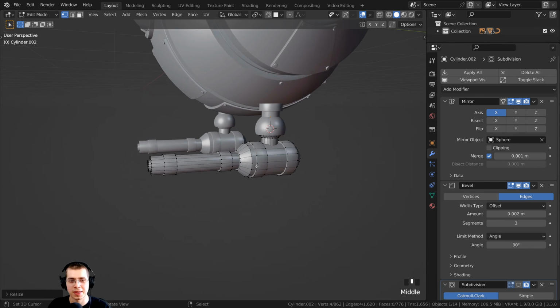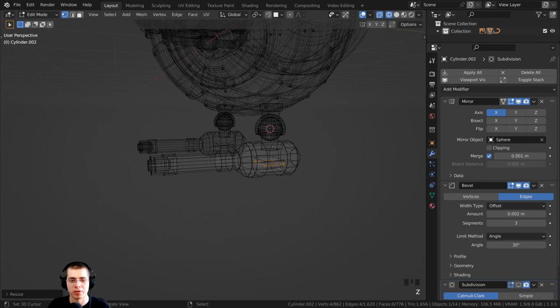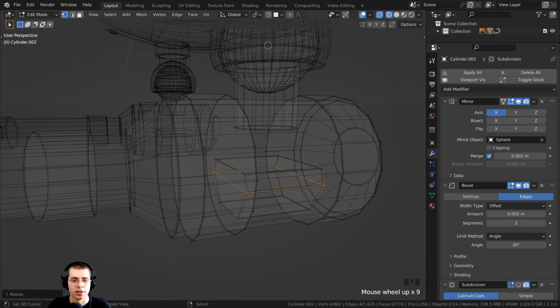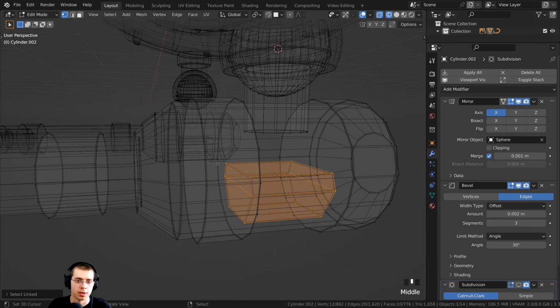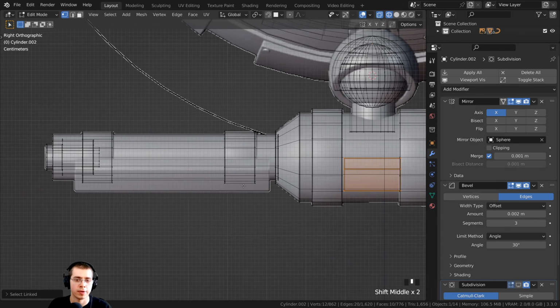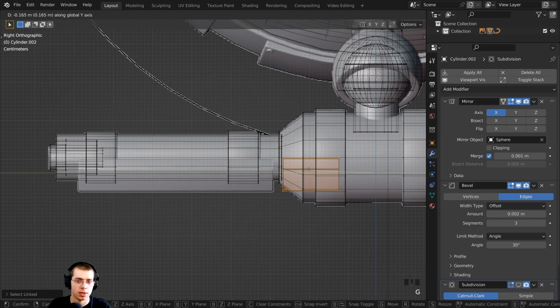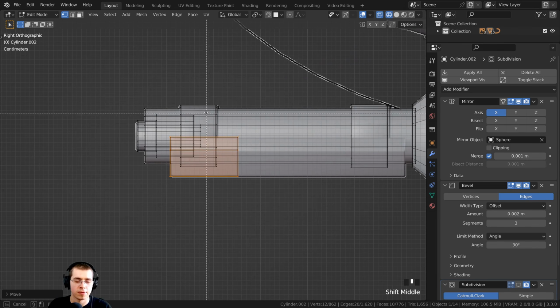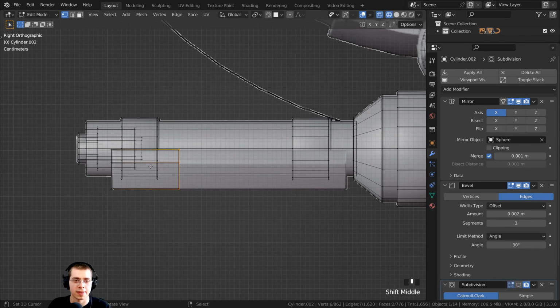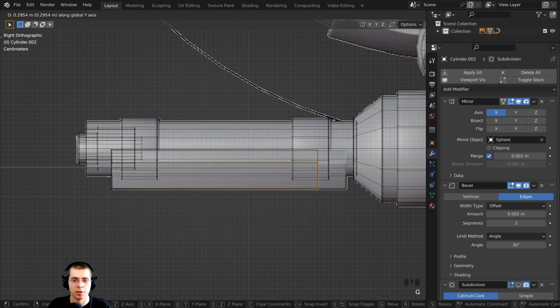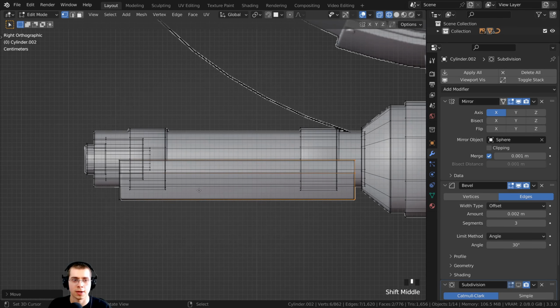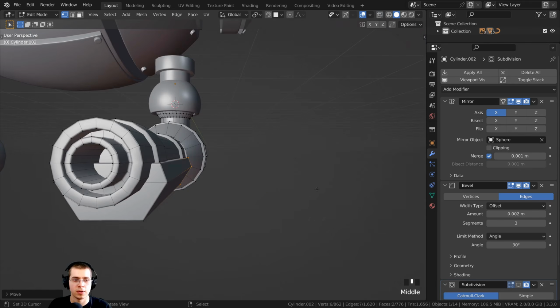And if I zoom out here, you can see that the cube is actually inside here. If I go into wireframe, there's the cube, and we actually want to bring it over here. So press the A key to deselect everything, and with your mouse hovered over this object, you can press the L key. That's going to select the linked vertices, and I can press 3 on the numpad for side view, and I want to bring this over. So I'll press G to grab, click with my mouse wheel to constrain it to the Y-axis, and we're going to stick that there. I can press B for the box select, and I'm going to click with my middle mouse wheel, drag over and let go just to deselect that side. And I can press G to grab, click with my mouse wheel, and bring that back and just stick it there. All right, hold down the Z button, go back into solid view, and that is looking good.